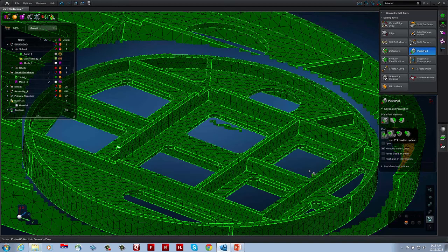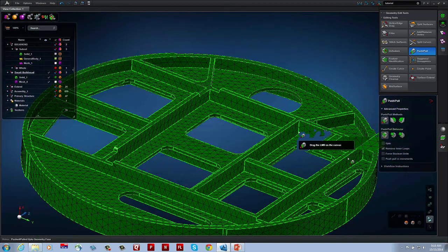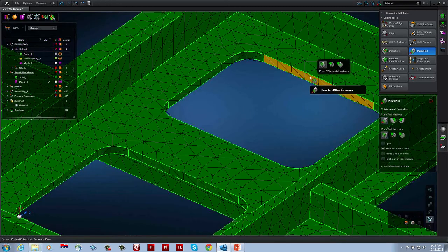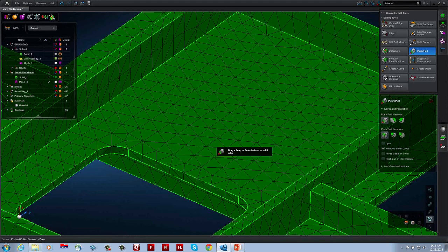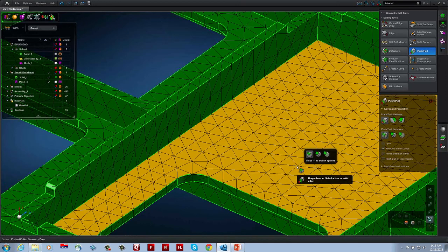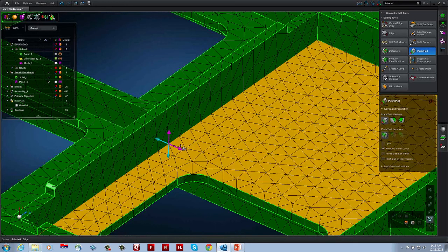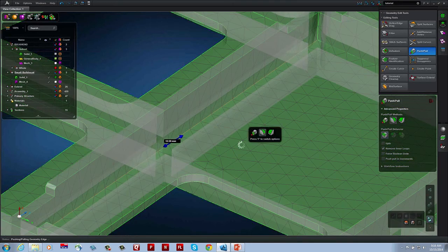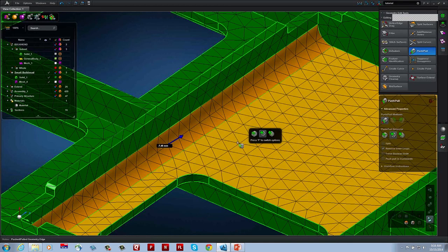So I've quickly added an additional flange using the up-to operations to make it a part of my solid. Although we have powerful defeaturing tools, the push-pull tool is also very useful. I can come in here and close up this hole, for instance, by taking that face and dragging it through. That hole is gone. In addition to operating on the faces of a solid, the push-pull can also operate on the edges of the solid and allow me to create a fillet, if I want to reintegrate a fillet into my model.